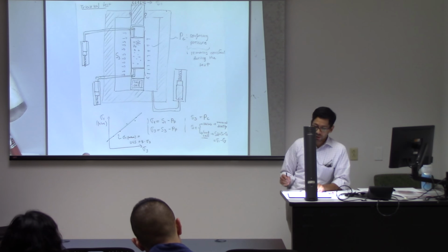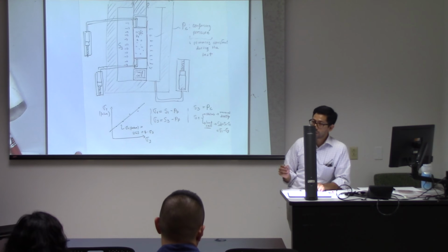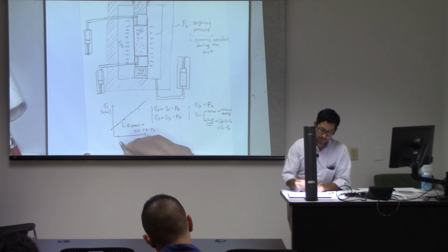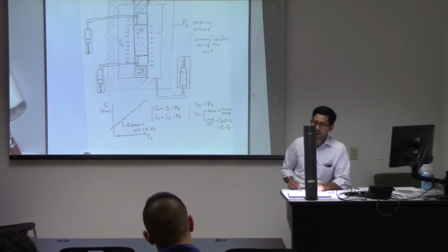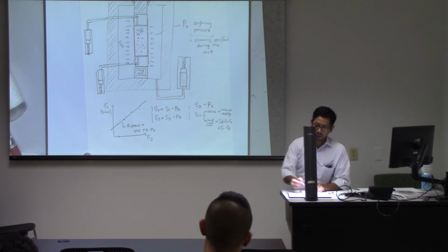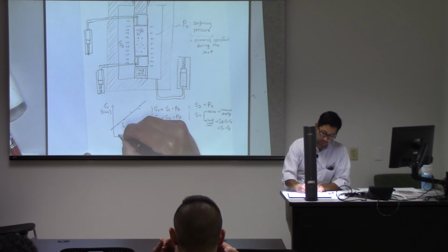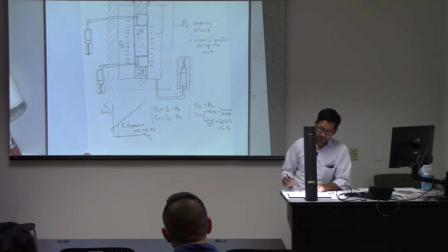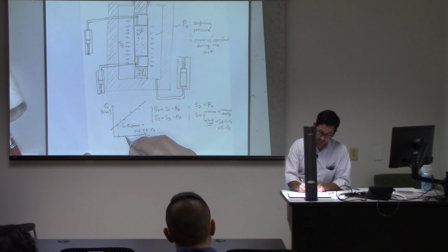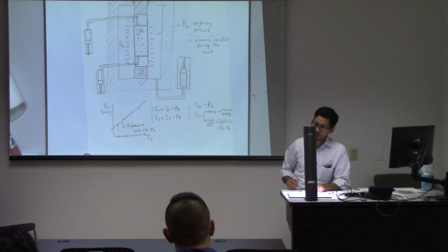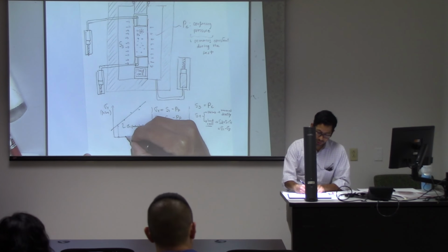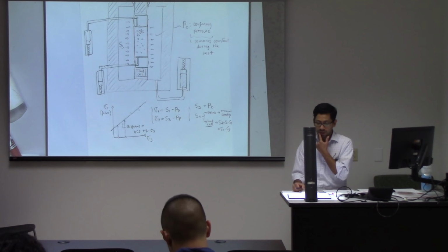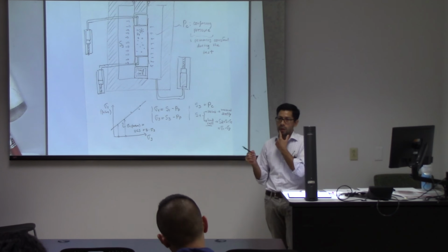And it remains constant so that, for example, when you start the test will usually start somewhere over here. And as you keep on increasing the axial stress, this will go up, up, up, and it will fail at that point. If you were to increase the confining stress and start over here with another sample, sigma 1 will go up, up, up, till it touches that line and it fails. But that one always remains constant.